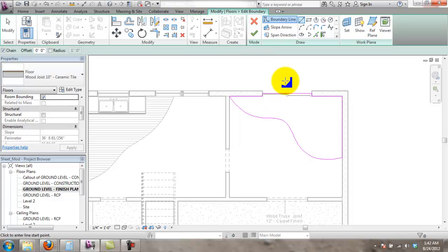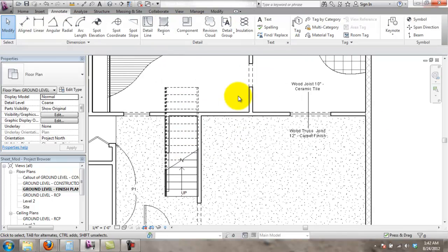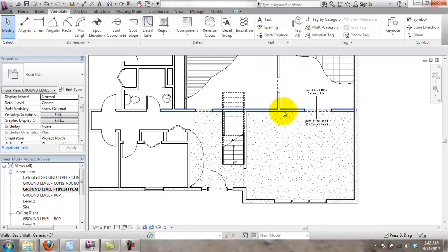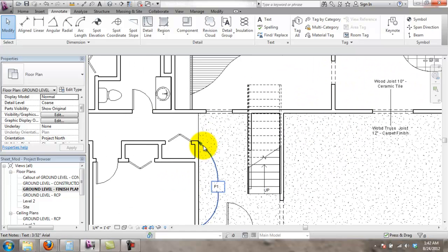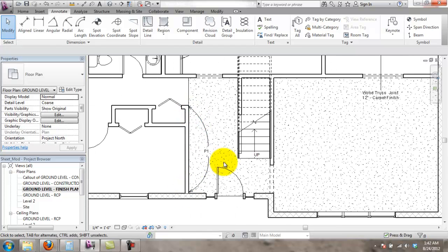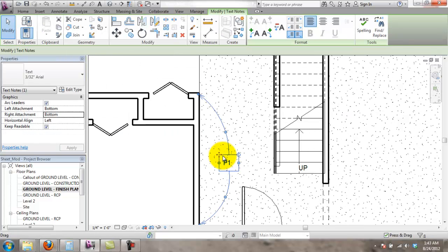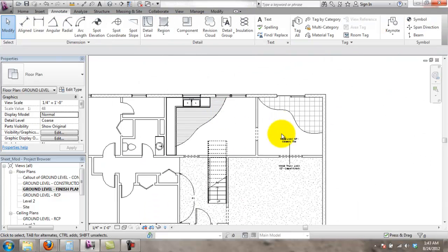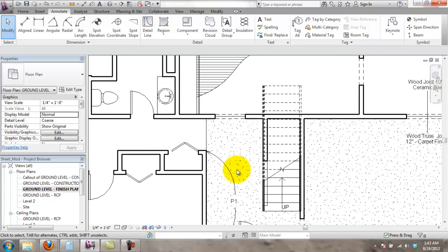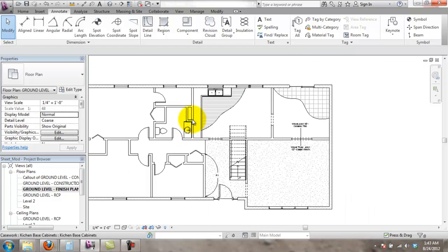Alright, so those are good there. So honestly, the finished plan is probably the easiest plan to create because this is what you create your tags from room to room, and any special paint that you have, you might call out, or any special finish you have, you'll call out with a note, and everything else refers to a general legend. For the most part, if the house is brand new, maybe every wall is painted white, unless it's a special wall, or even in a bathroom like this. You can see that you would have some kind of special wall. So for the finished plan, this is okay for what I'm looking for.